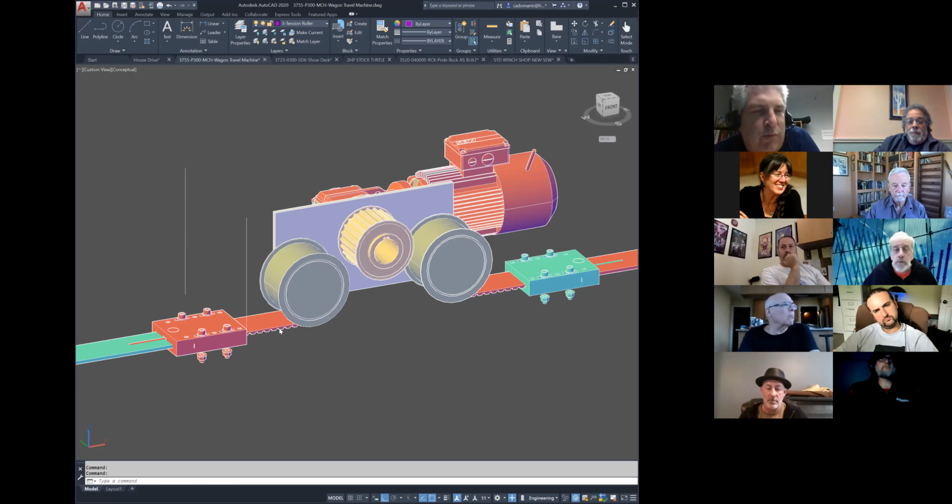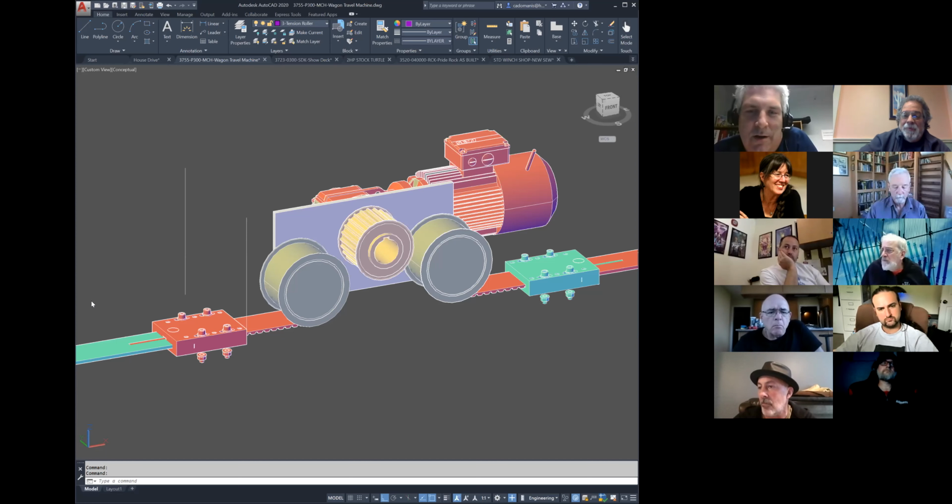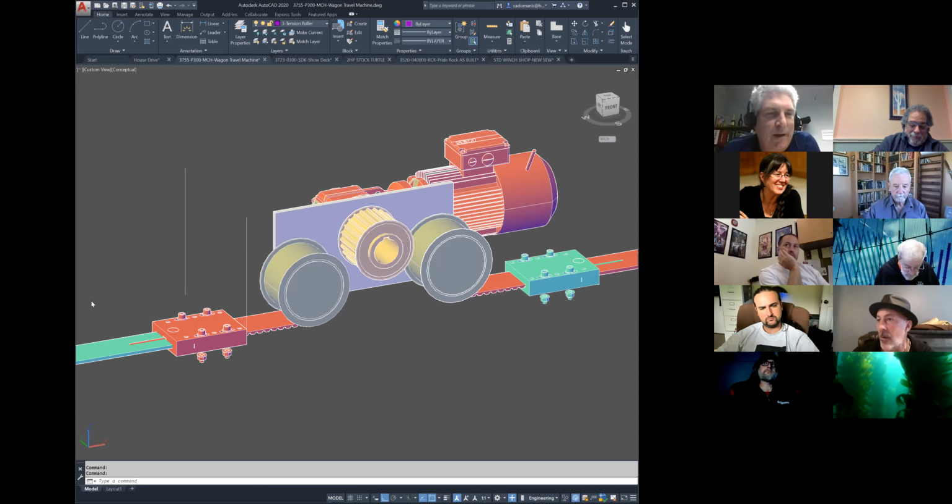Some of these belts are priced by the millimeter, with dollars attached to those millimeters, as opposed to the cents or quarters we're paying for a foot of cable, so you just can't compare. So when you look at it and think, well, maybe this pulley was only $200 instead of my $1,200 drum, if I have to spend $3,000 on my 80 feet of belt, that's a whole lot more than the $80 of cable I had to spend. So that's where it sort of falls apart, at least in our experience.